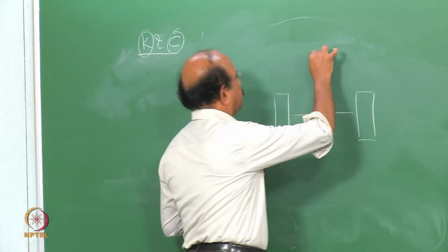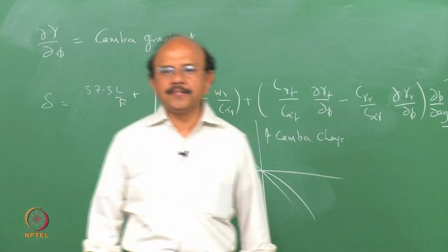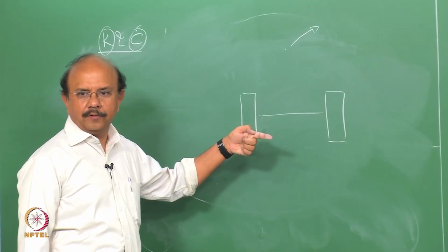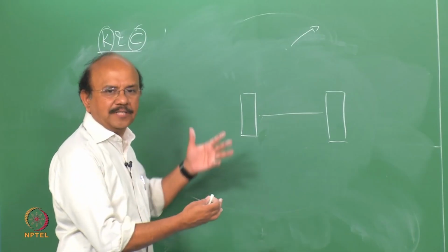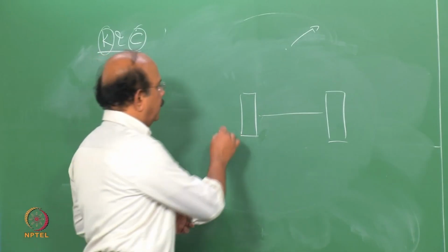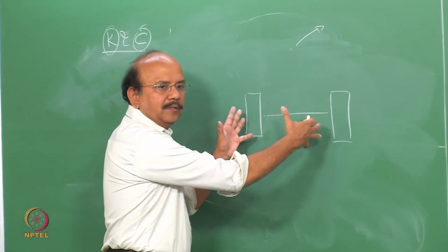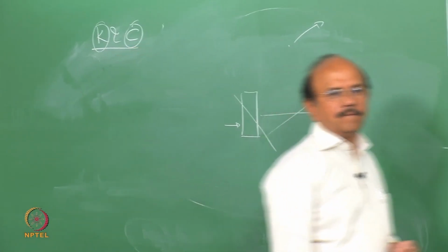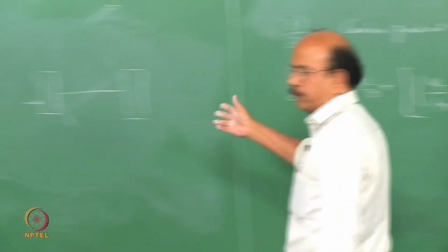Okay, now this is going to take a turn like that, which means that there is going to be a force that's acting in this direction. Right? Now, if the force so happens to act, and if there are deformations due to which the tire is now deflected, say for example this whole thing is deflected like this, again it's obviously going to have an effect on the understeer gradient.